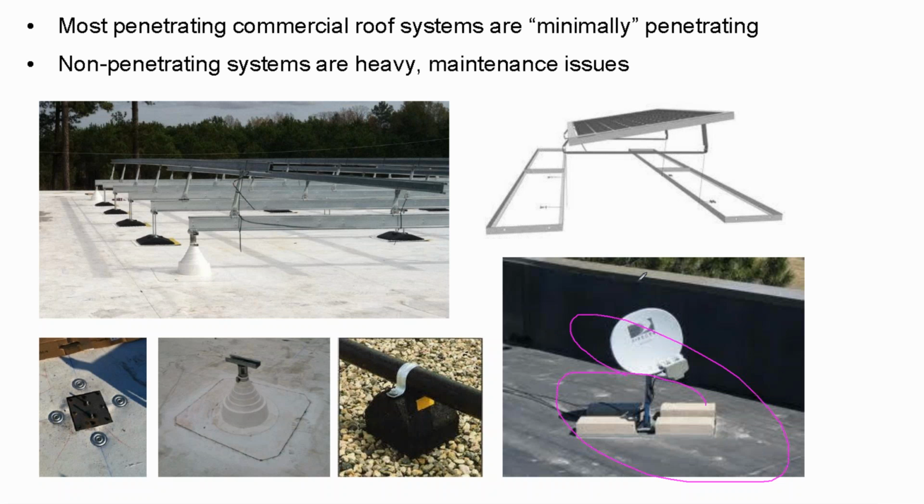in the early 2000s, mid 2000s, your large commercial solar inverters would be negatively grounded, and it would create a blind spot in the ground fault detection system. And what would happen is you got aluminum conduit on some systems.